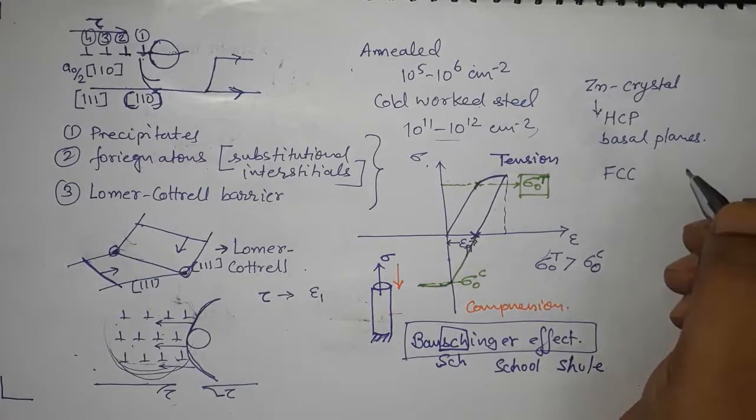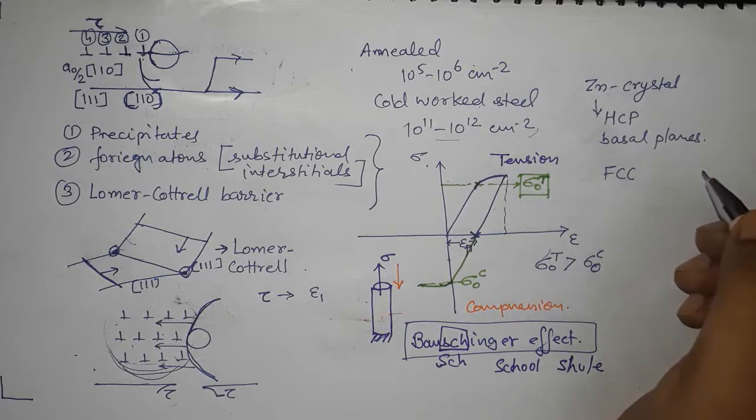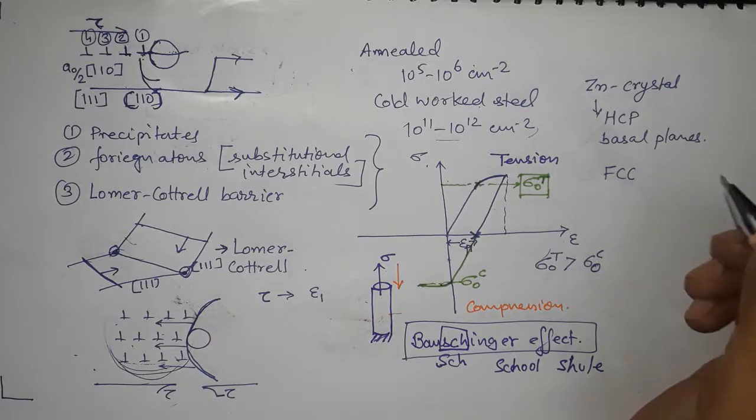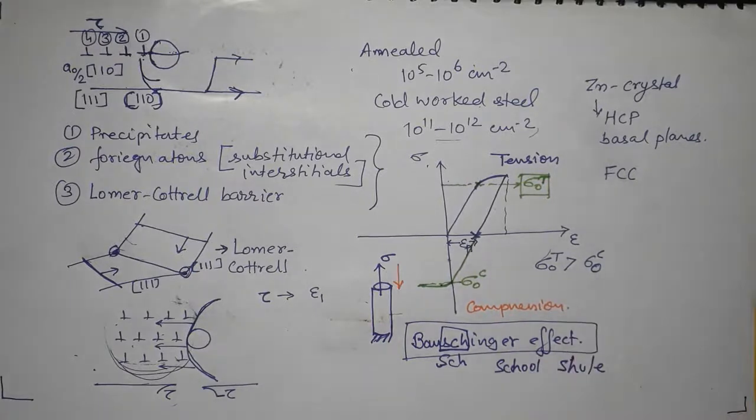But the concept of back stress in single crystal explains the strain hardening, and we will see how that is the most prominent or most effective reason of strain hardening in single crystal, and whatever happens in single crystal also happens in polycrystal, apart from other things which can happen in polycrystal, for instance grain boundary interference with the things. Okay, so let me go to the next page.